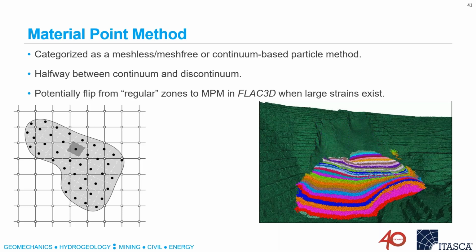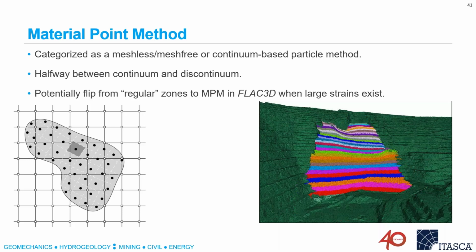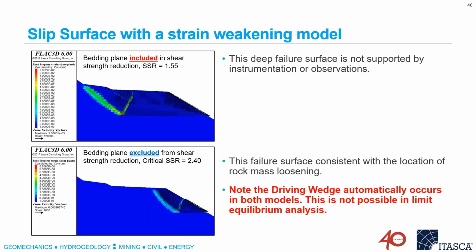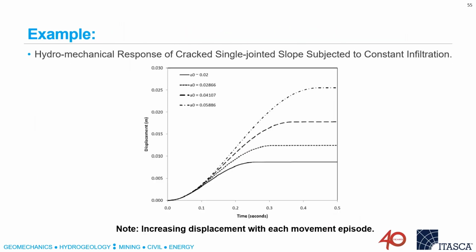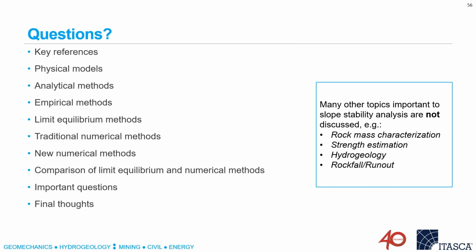And then you mentioned explicit inclusion of joints in 3D modeling using 3DEC. How would you account for strength anisotropy at a smaller scale with intact rock for a large scale model? Right. When that question comes up, what we've tried to do is analysis with what's called synthetic rock mass. You make a sample which you hope is representative of a portion of the slope.